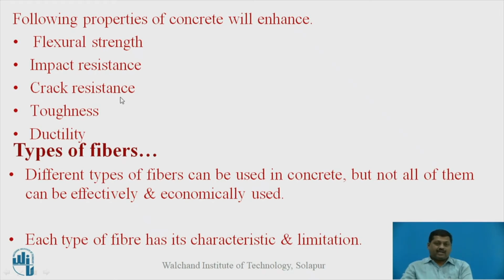Cracks will not propagate because of the fibers. Then the toughness of the concrete, and a more important property, the ductility of concrete, will be enhanced. Concrete is brittle in nature, so if the addition of fiber increases the ductile property of the concrete, that is the better advantage.